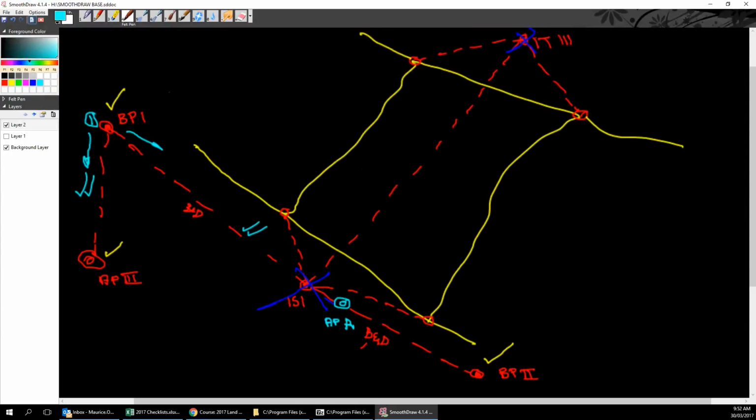There could well be, maybe through here, a vehicle entrance or something like that. Our curb and channel could be out here like this. This could be our road, curb and channel in there. So that mark might have been taken out when they constructed the vehicle entrance or something like that. So we might put that mark in there, and we probably need to traverse around through this thing.